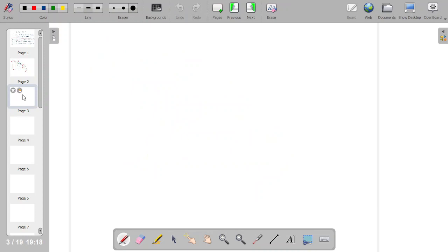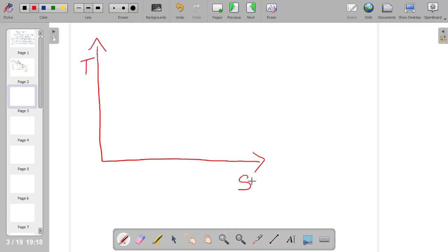Now go for the TS diagram. So we have drawn the TS diagram of Otto cycle. Similarly here also we have to draw the TS diagram. These two diagrams are very important. If you are not drawing these diagrams, you may lose considerable marks in the exam. So the first process is the same as that of Otto cycle. Entropy is constant, isentropic compression, temperature increases.